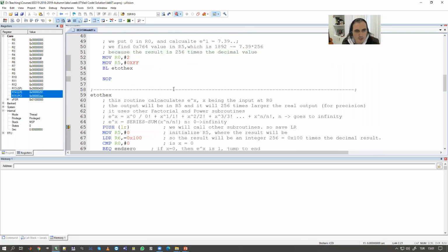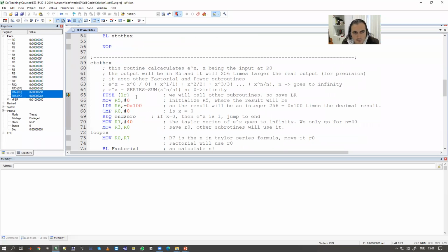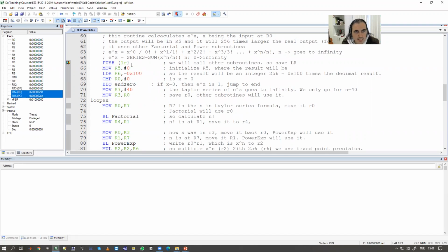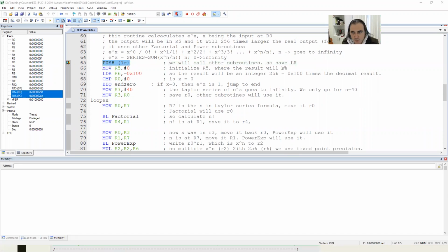Okay. So we are at this first line. We lost those values, but they are in the video, so you don't mind. So guys, I'm also doing something else at this point. I'm writing the value to the stack, which means there's a value inside LR, which was this value, remember? And there is the memory where I have the stack pointer, right? So let me draw the memory of the stack pointer here. So this is the memory. Imagine the stack pointer is pointing to this location.